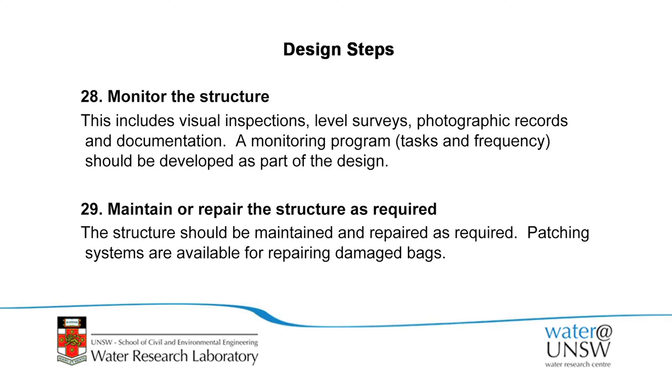Once it is built, monitor the structure. I would always suggest developing a monitoring program. It can include visual inspections, surveys of the crest periodically, or documentation. The monitoring program should include what tasks you're going to do to monitor it and how often you should do them, and that's really part of the design. Some of the standard coastal engineering references, like the Coastal Engineering Manual from the USA, do say you can make a structure where your procedure is no monitoring at all. As long as you accept you're going to have no monitoring, or just purely reactive monitoring, where if someone rings up and says it's damaged, then you do something, that's acceptable if it's been a well thought out decision.